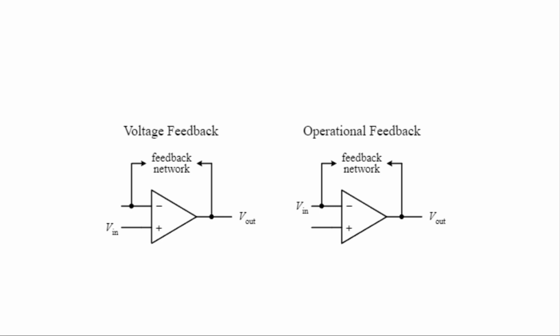V negative in the formula changes now because the output voltage from the op-amp is giving extra voltage back to the inverting terminal. What this means is that you must replace V negative with F V out, where F is a fraction of the voltage sent back from V out. Since you're dealing with negative feedback, you can apply Rule 4, which says that the output will attempt to make V positive minus V negative equal to 0.